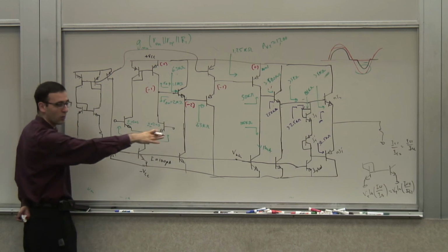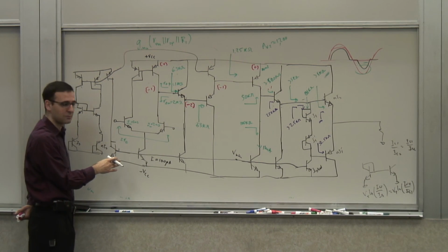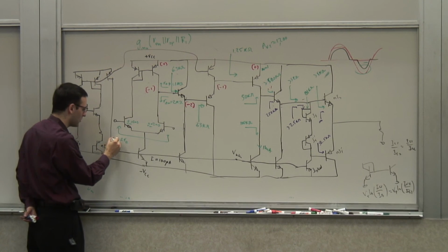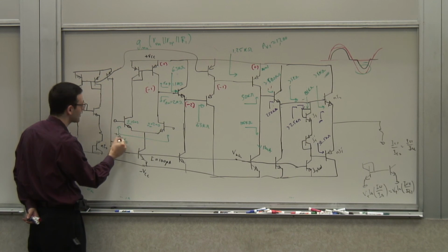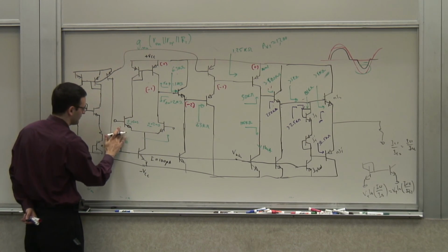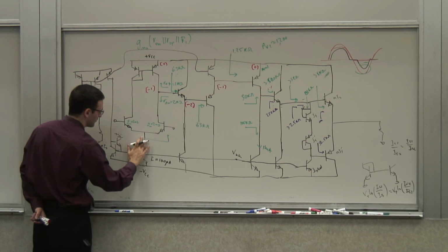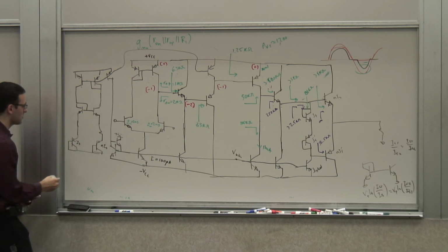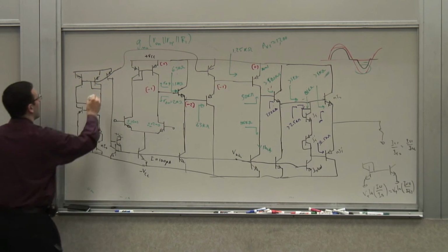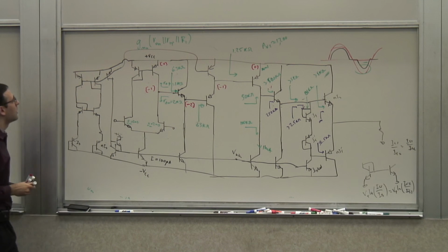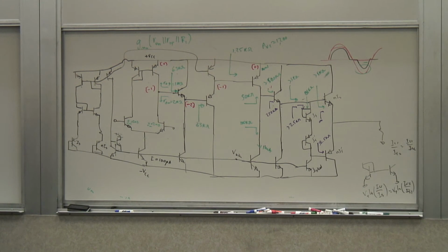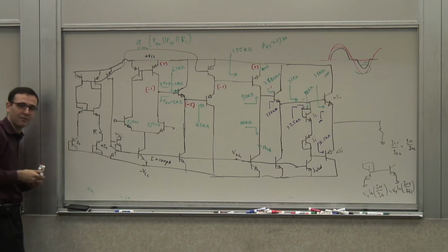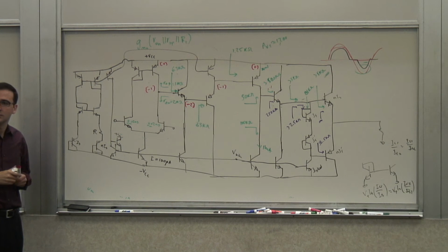And then since this is driving a whole lot of current sources, I know that I probably need a lot of base current, so I can use that trick. I can put another transistor here, to VCC, so this is plus VCC. That would be a current source, and this is connected here, that's connected here, and I don't think I have anything other than transistors. Well, I have a resistor here, but I can't have resistors. So this is my entire output.